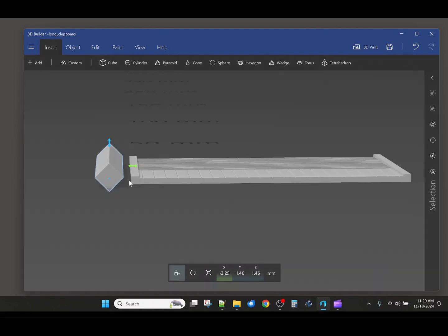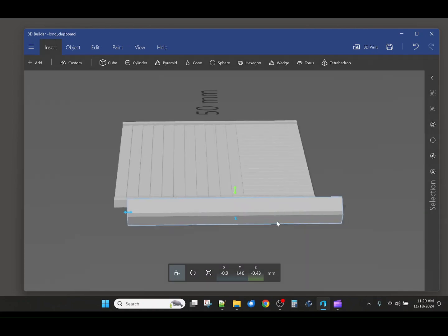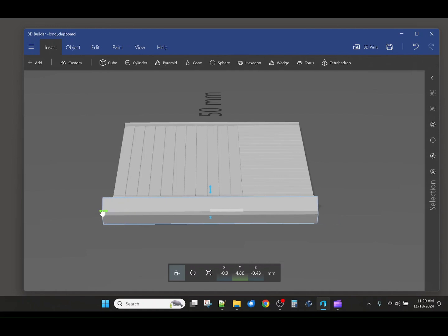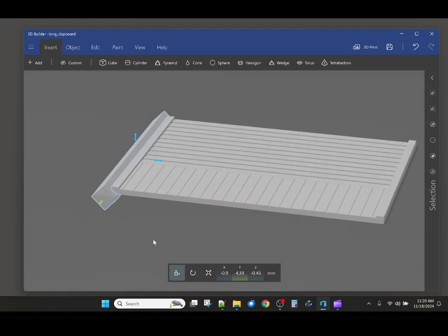This positioning requires us to move it vertically so that this surface covers the entire subtraction in the wall. We also need to move the whole board up in order to cover the entire corner. The final movement is the movement to put the very edge of the corner trim at the top of the subtraction. Zoom in to do these movements because you'll get more precision in the move if you're closer to the object.